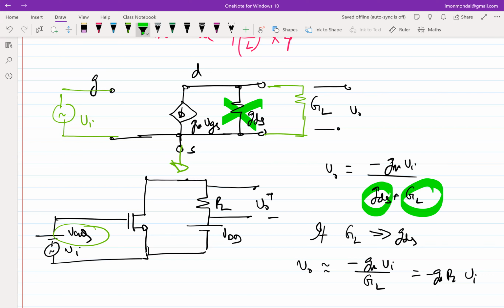This might not be significant with only one transistor, but if you have 6 or 7 transistors in a network, you can significantly reduce the number of nodes and equations by making these approximations. Knowing the load, how you plan to drive it, and the typical GDS you can get can significantly improve your design process.